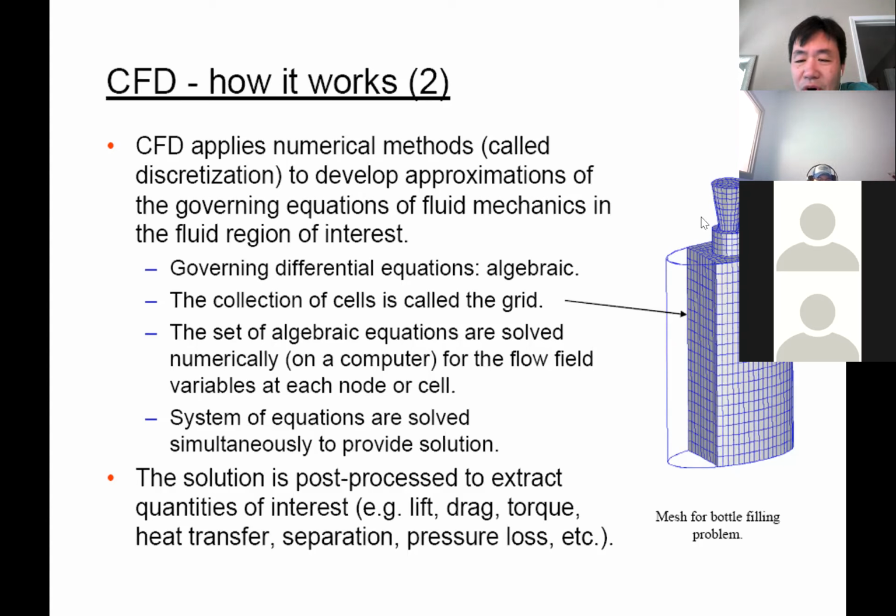So the finer your mesh is, the more data you will get. The finer it goes, the higher the resolution of the data you will have. That's one good thing about using a fine mesh, but there's a bad thing about using a fine mesh too. I will talk about it later. So that's how it works. You have thousands of data points.